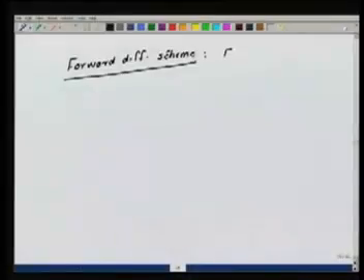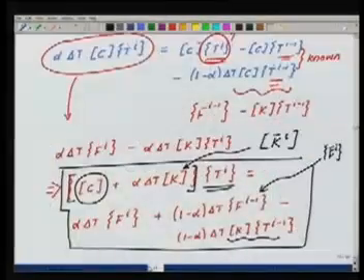So this is what the forward difference scheme is called, an explicit method. It is really explicit when I do not need to invert the matrix C. If alpha is equal to 1, if I go to the backward difference scheme, then you see that K is also sitting here. K in general will not be diagonal, so it will make this whole matrix K bar non-diagonal. Then we have to do the inversion.